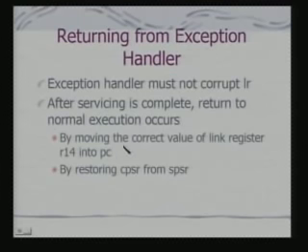And there is a subtle, interesting point here. What I have written is that I am moving the correct value of link register R14 into PC. It is not that I am loading exactly what is loaded in LR into PC. Why it is required, we shall understand when we study the pipeline architecture.